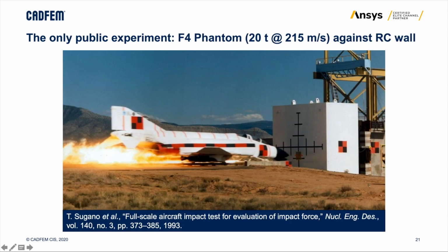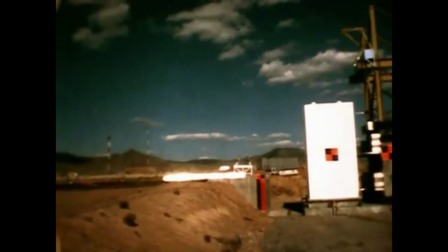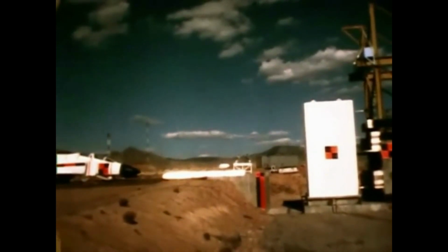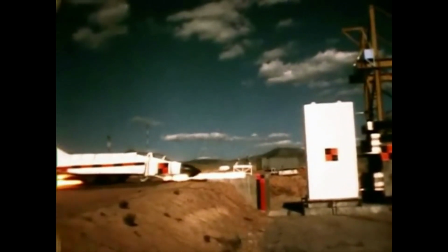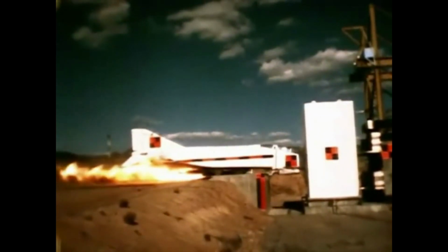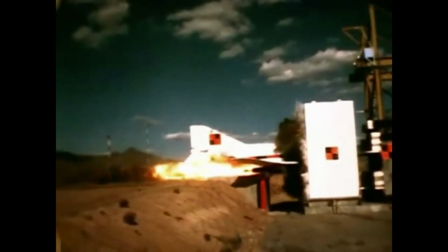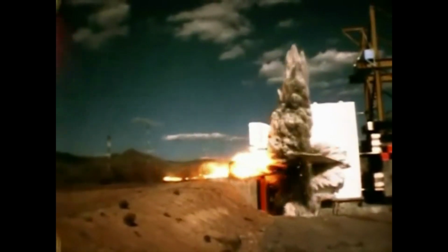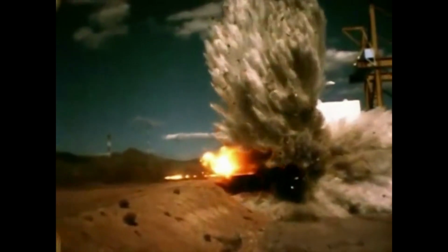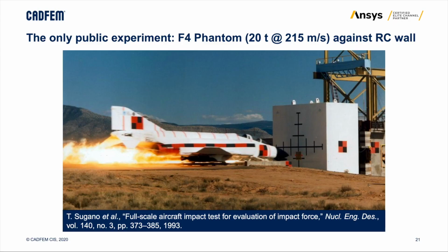On this slide you can see the video from the only publicly available experiment with a Phantom F4 impacting a reinforced concrete wall. You can see that the aircraft basically does not decelerate during impact, and that after the impact it transforms from a solid state to dust.